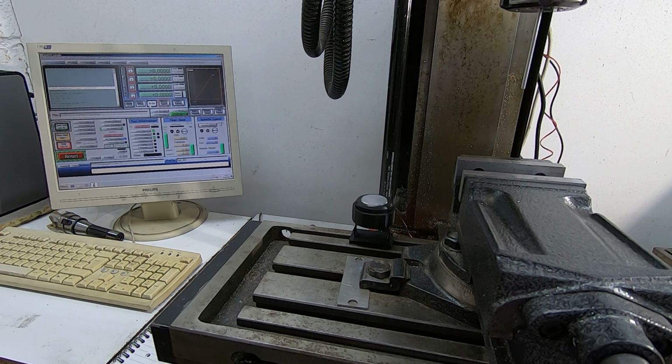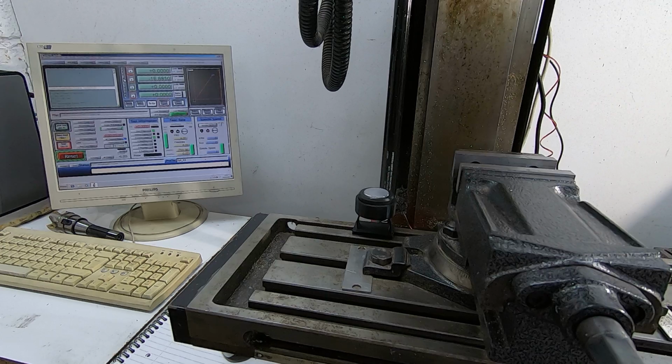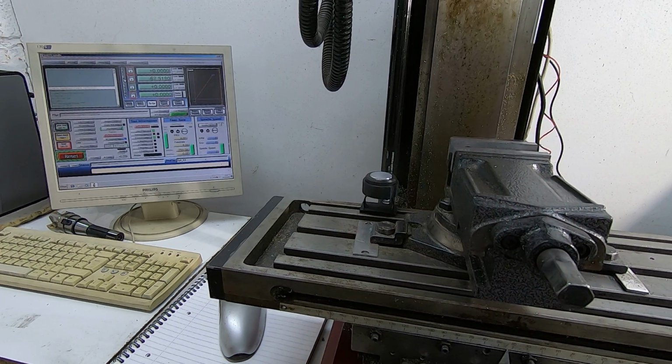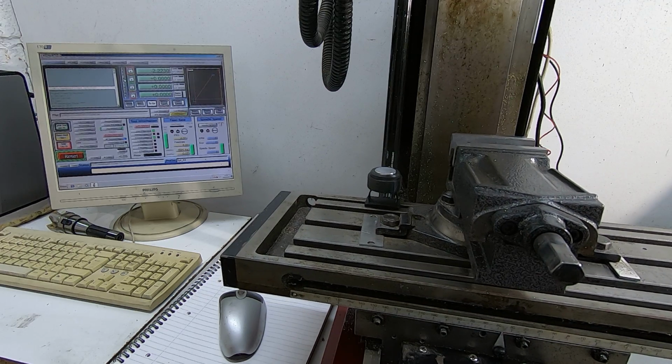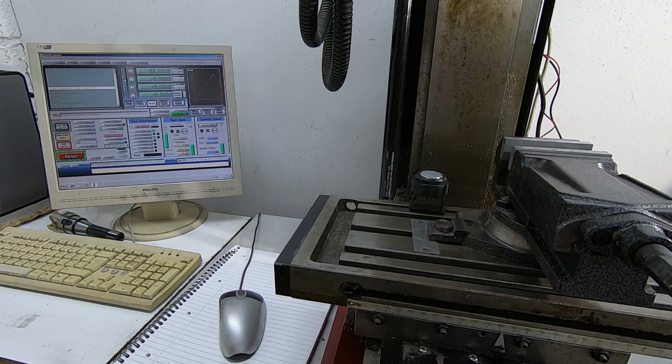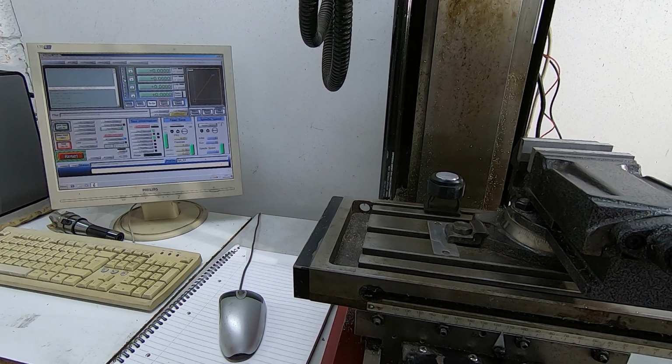So using these macros, you do need to drive it to reference all home. So click on that and the machine will just physically drive to the 3 home limit switches. Just takes a few seconds. Otherwise it will use the default values when you power it up, which is where you left off.